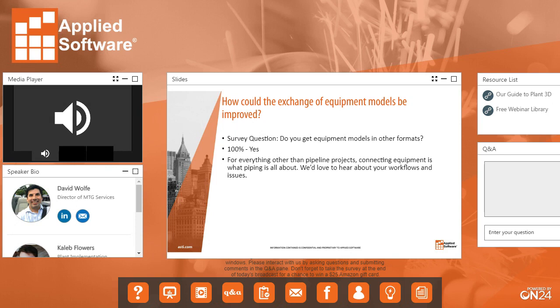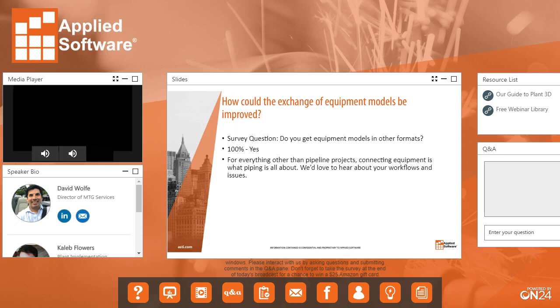That's definitely true. Yeah, I've absolutely had that in the past, with equipment where they're like, we don't really know exactly what it's going to look like, but we know that the nozzles are going to be here and it's going to be this big. So sometimes it's best to just kind of cartoon it in and make it look right, make the sizes, as long as you're getting your proper area there, and just move on. You can still have all of your information, all of your data, your sizes, your speeds and things like that, but just get it in there, get the space taken.